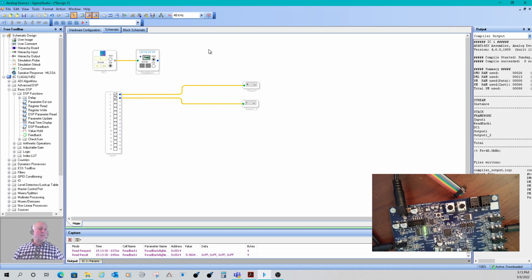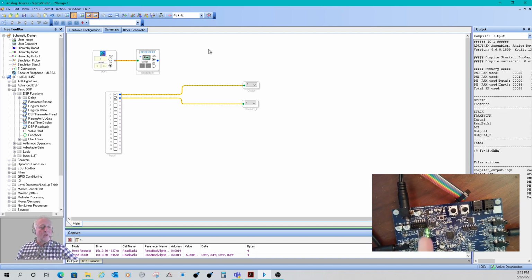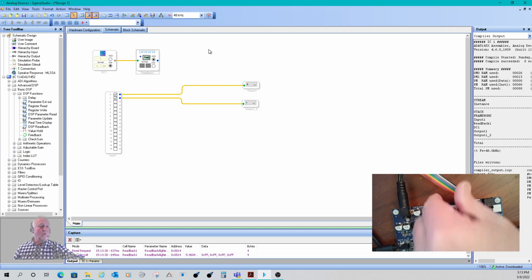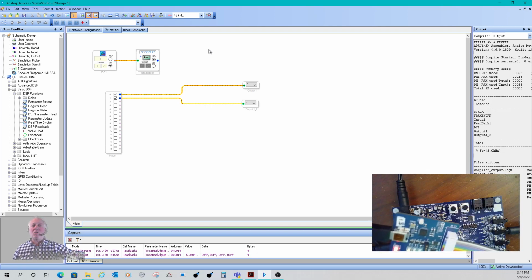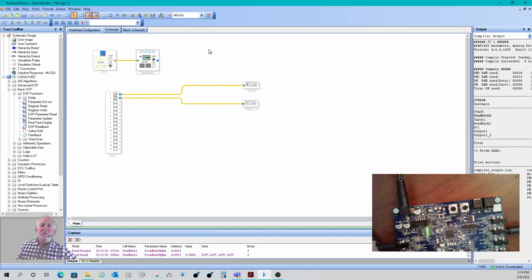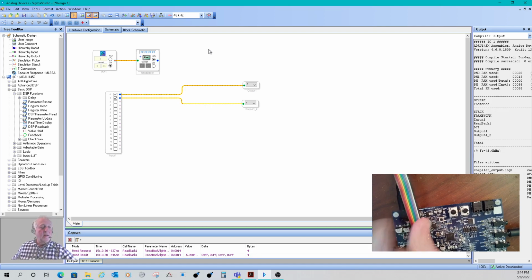So now you start asking yourself, is the power jack plugged in? Am I getting power? Lights, and you can obviously measure it. But one of the things is, is the USB-I hooked up to the USB port, and is that connected? And obviously in this case it wasn't connected. Now, I don't criticize anybody for making these what seem to be stupid mistakes, because, honestly, been there, done that.